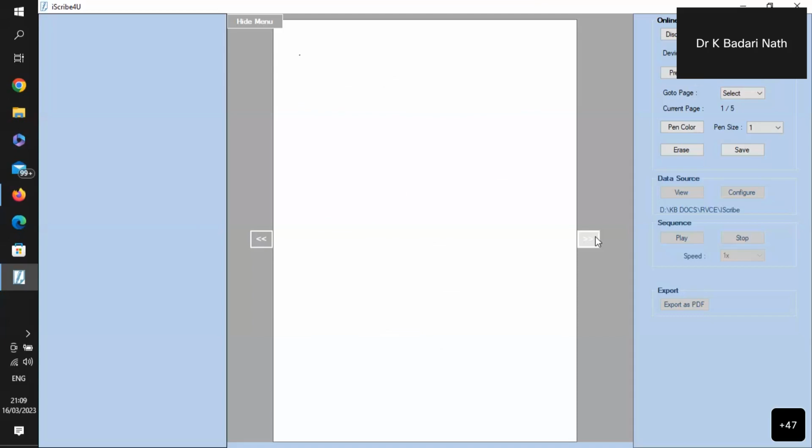Now I'll take a little bigger operation: Add R1, R2, and the answer is stored in R3. So now I want to perform addition. In the previous case, I did not perform addition; I just moved the data from register to register. I understood what control signals are supposed to be given. Now I have to identify how many steps or clock cycles are required to complete all the steps needed to perform the execution of this job.